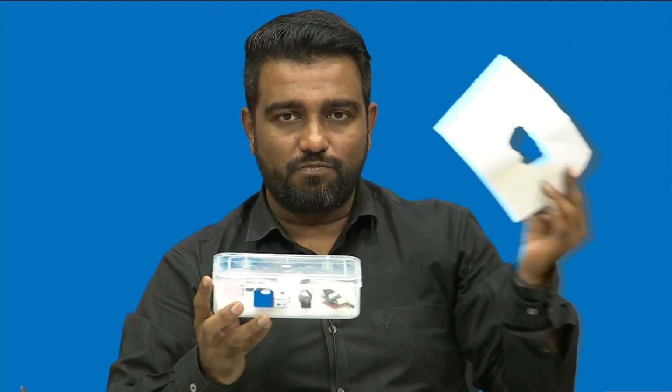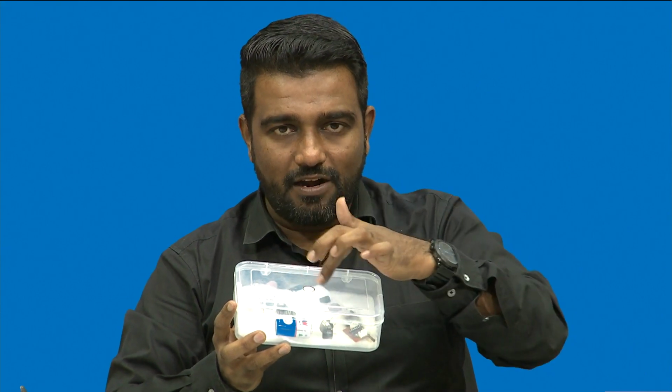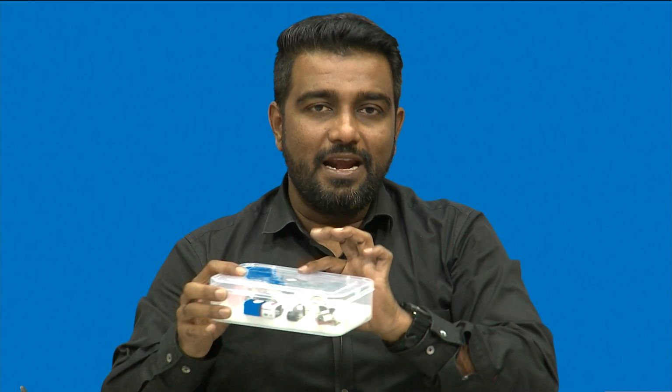So when I remove this mask, I will only have the central region with the sensing layer, right. Now if I heat this at a particular temperature, I have my sensing layer ready. So screen printing is very easy to work with compared to thin film, right, but there are disadvantages, like in thin film you can have an extremely minute sensor, in thick film it is kind of difficult.